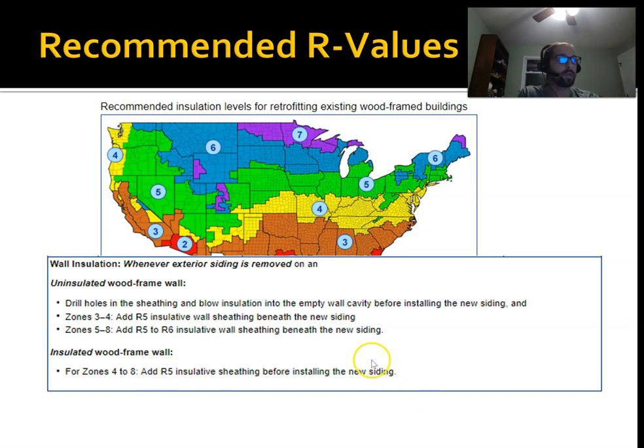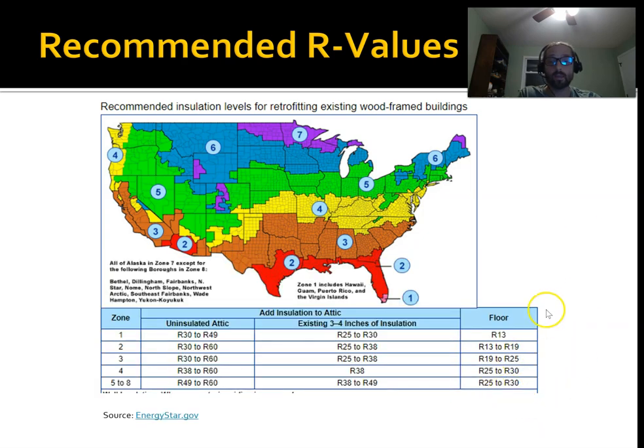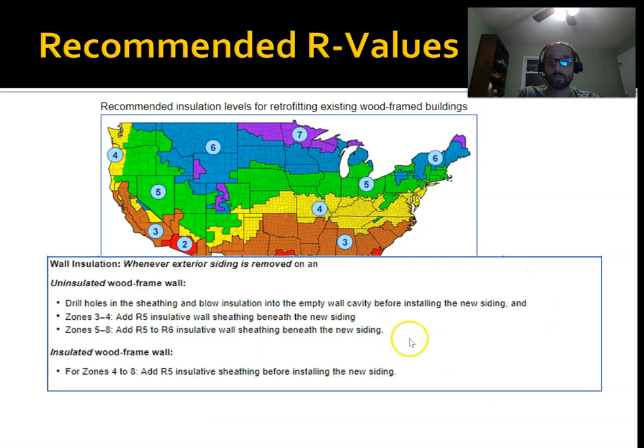And that's a really good way to prevent thermal bridging and maximize your insulation, because you're limited. If you have 2x4 walls, which almost all modern construction is, you're limited to 3.5 inches in your wall, and that's only going to give you about R10, 10.5, and that's not enough. In the wall you want to add more insulation than that. R10.5 is really not very good insulation.